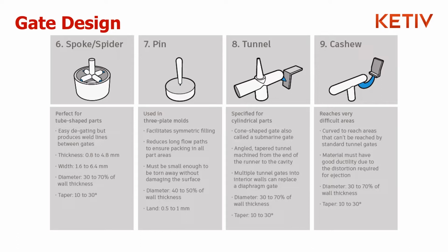If you look at just tunnel gates in this slide here, there's at least a half dozen to a dozen different forms of tunnel gates to explore that some folks actually consider one having advantage over another. And there's some merit to that and data that you can create based on simulation. But this is just one small function of a mold in process that extends through the process, fill, pack, and into cooling or solidification that impacts cycle time, part quality, performance.